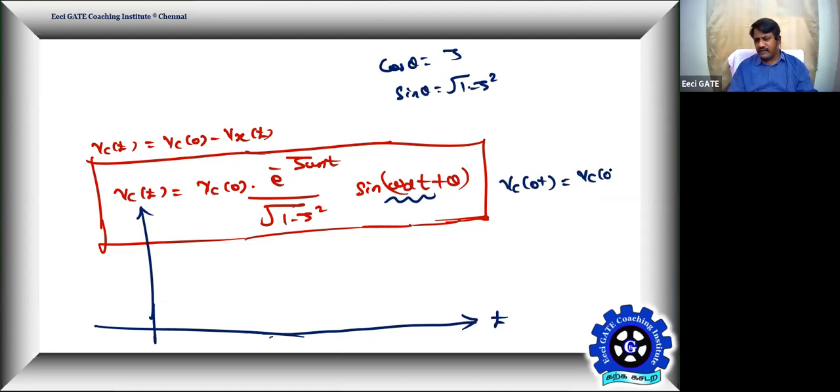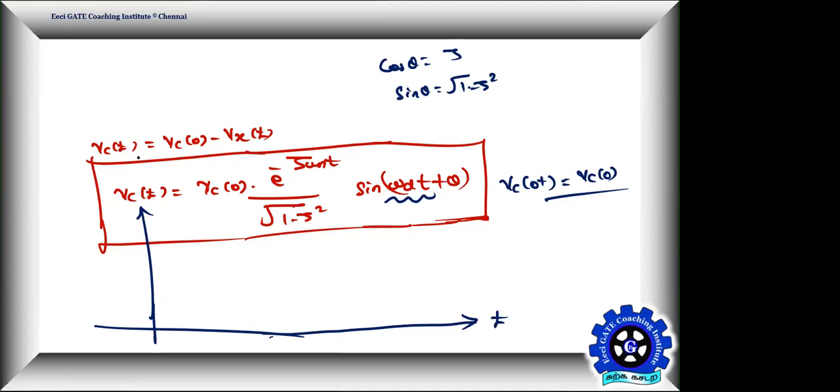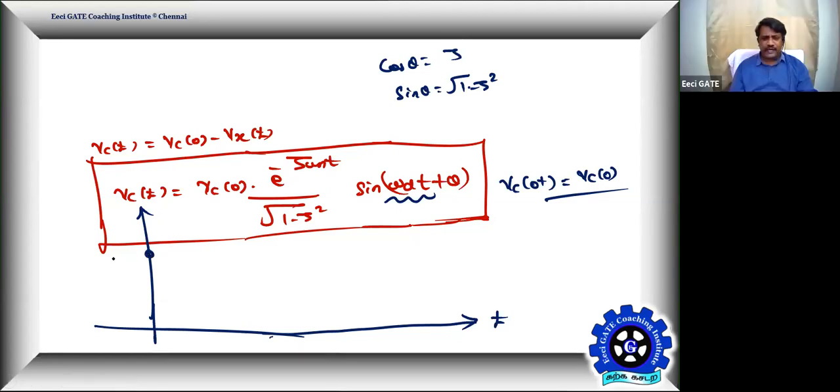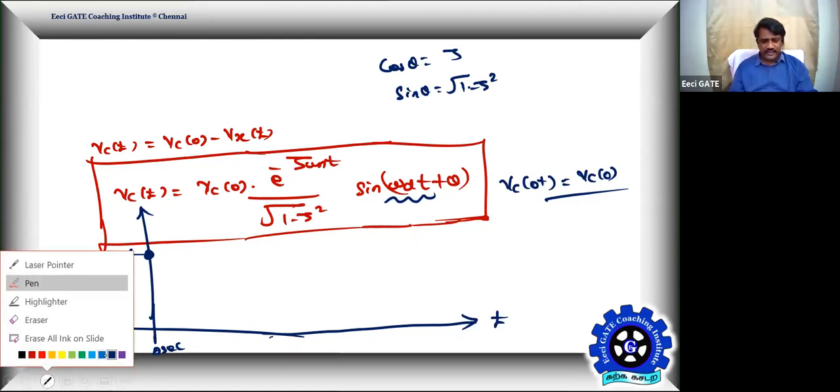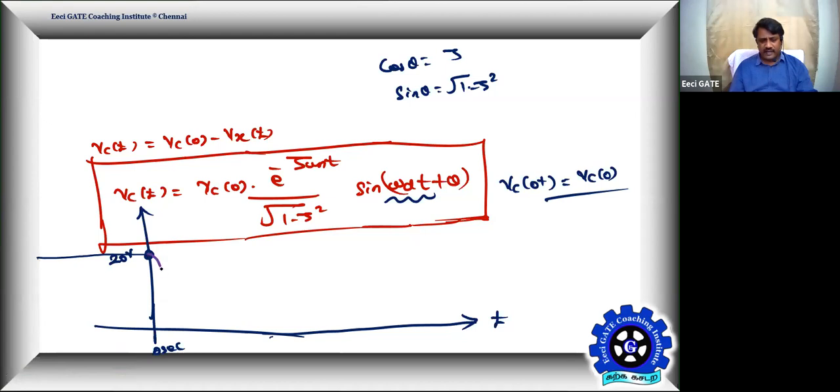It is going to begin with Vc of 0. The capacitor begins discharge. It has to begin there only. Initially it is discharged to 20 volt, as per our problem, long before. Then the time begins for the discharge. Then it is going to discharge with this transient. The discharging transient will be this. It will fall and oscillate. Negative is also possible. And then it will reach 0 after the time 5 by zeta omega n seconds.